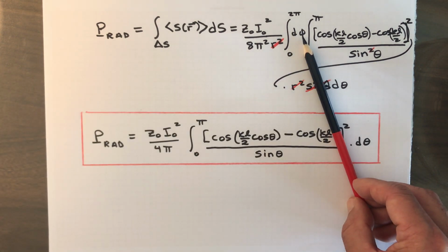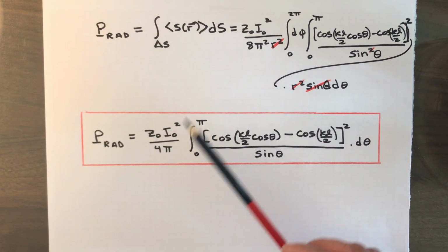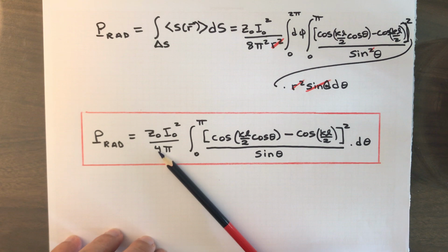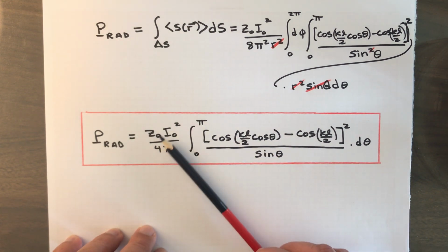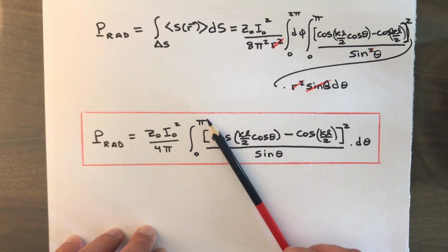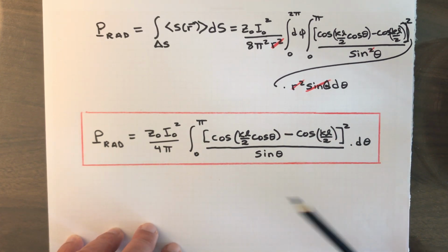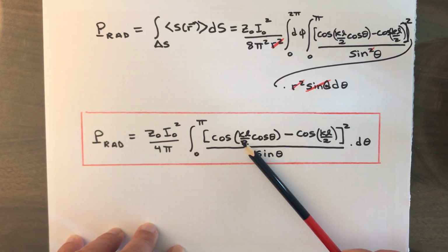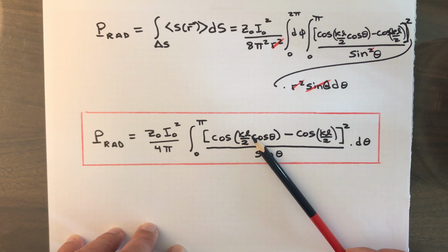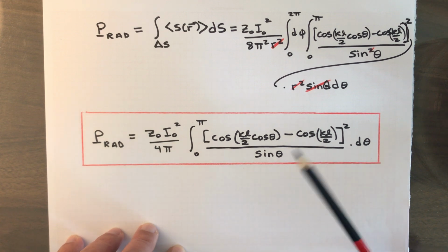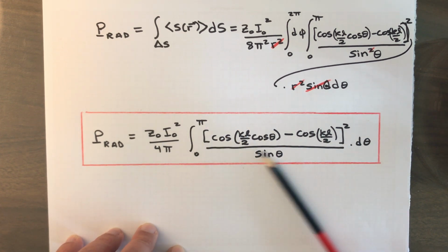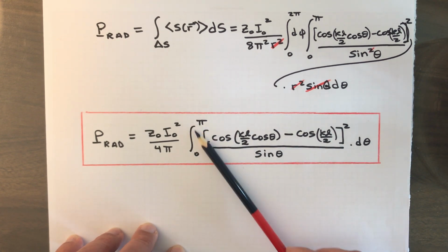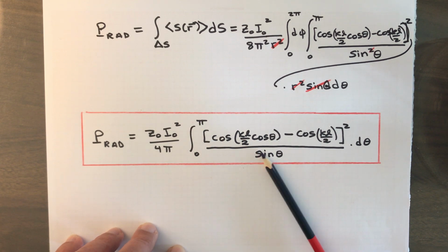We of course see then that as we write this down, the 2 pi will cancel one pi down in the denominator, and 8 becomes 4, and that's our expression. And that is a definite integral that we write down in our expression. Notice here that you have an expression that has k and l. So if somebody gives you the wave number and the length of your dipole antenna, you can go ahead and evaluate this using Wolfram Alpha, an integral evaluation tool online, or mathematical tables, what have you, and come up with a number. So this entire expression is actually just a number, okay?